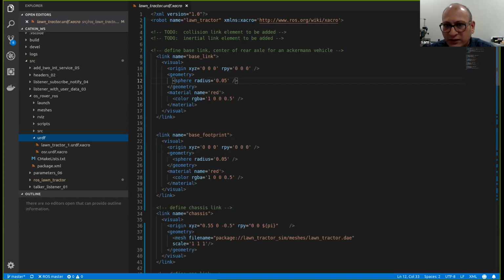That's mostly used if you are designing a biped or humanoid robot, that would sit right at the ground, so that if there are any obstacles while the robot is walking, it is able to avoid them. That's the main idea behind the base footprint. It's basically just the downward projection of the base link, in most cases I have seen.